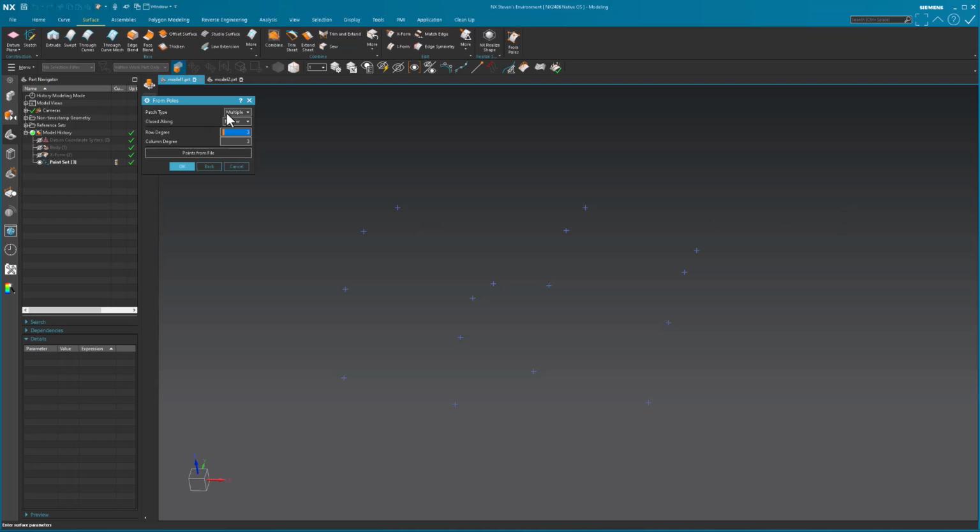So what I want to do now, because this is an old tool called From Poles, you'll notice I extracted the point set to get my control points. It's the easiest way to represent what I want to show you. And I'm not going to do multiple, I'm going to do a single patch to really simplify it. Notice everything goes away because it's a single. We'll overly simplify it and make a bold statement that someone's probably going to spurt out at: oh, it's not Bézier. It's in essence making a Bézier surface. Okay? In essence is what it's doing.